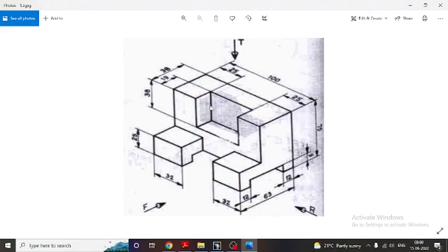These two cuts again depend on which plane you are going to select. If you want to select this top plane, you need to make this rectangle, or if you want to select this plane, you need to select this plane. So it depends on the person. If some person selects this, he may draw this rectangle for the cutout. If the student selects this face as the sketching plane, he needs to select this rectangle for the pocket.